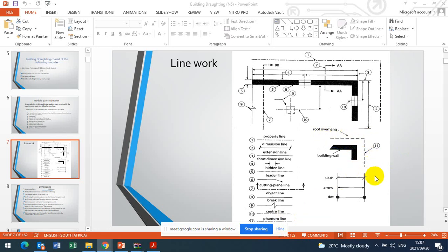You'll see when you print that the plot style is going to pick all our layers nicely, because our printers have been set to pick up these layers. Like green will be thick, red will be light. We have set everything by default. That's why you do not change the thickness of any of the lines or layers. Okay. All right. And then the rest of the lines, you have done them in general drafting. You will have to go through and just check. These are the important ones: the property line, the building line, the brickwork, the windows, and the roof edge layer.